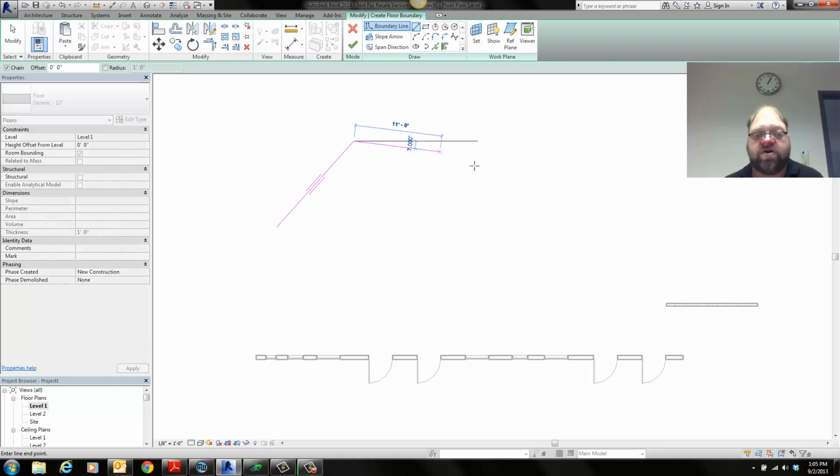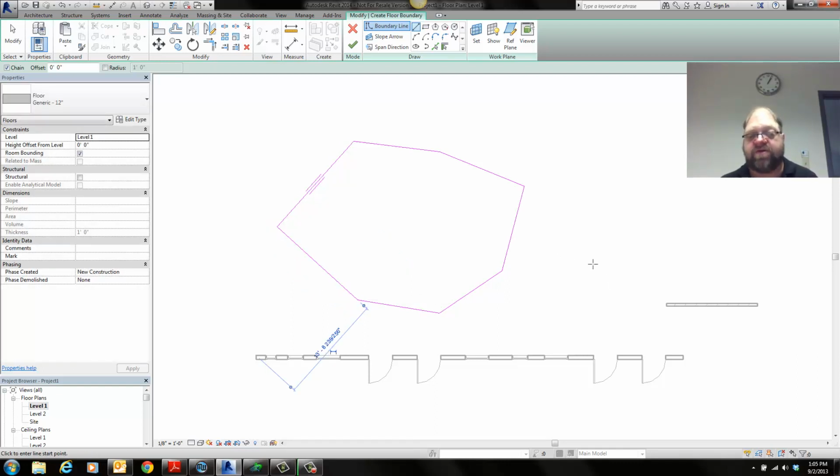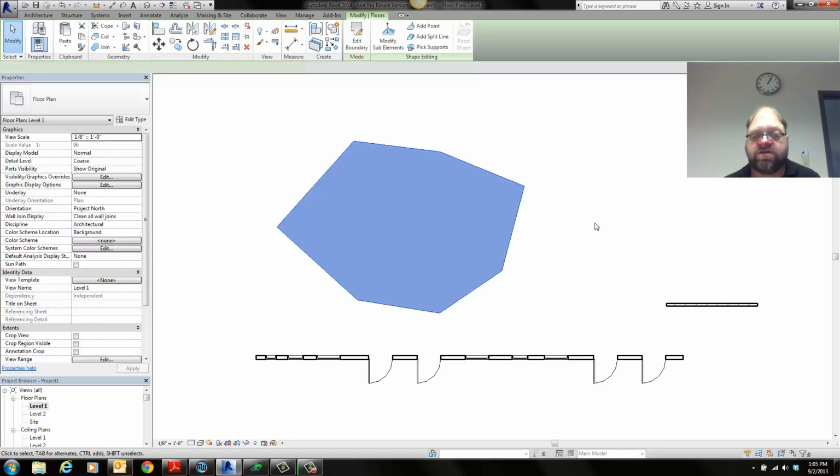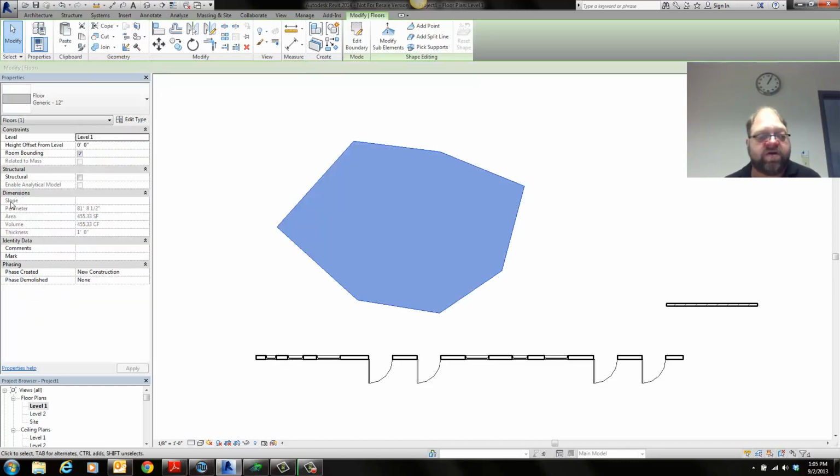I can draw an outline for what the shape of the floor is going to be, and I'm not specifically defining a width and a height or anything like that of the floor element. I'm just describing the outline. So the actual shape or the dimensions are somewhat implied, right? So it has some type of perimeter, and it would never list a width and depth because it doesn't know what directions I'm talking about.